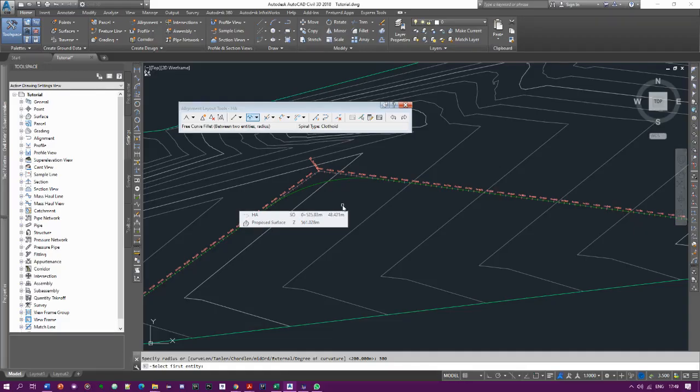Those values in the handbooks have been specified based on the speeds you are designing for. So what's your design speed? That would determine what your curve radius should be. And so for your project, please don't just use random figures.